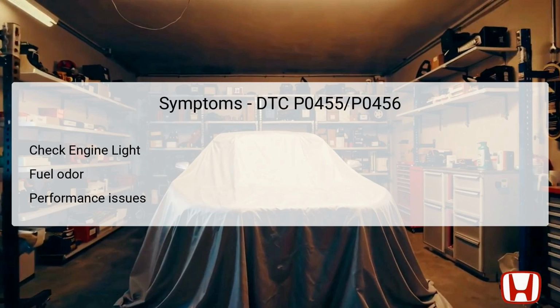Symptoms indicative of DTC P0455 and P0456 may vary, but one of the most common signs is the illumination of the check engine light on the dashboard. Drivers may also notice a fuel odor, especially after refueling, which can signal a leak in the EVAP system. Additionally, there may be performance issues such as reduced fuel efficiency or unstable engine performance, as the engine may not be able to manage fuel vapors effectively. Being attentive to these symptoms and addressing them promptly can prevent more severe issues later on.